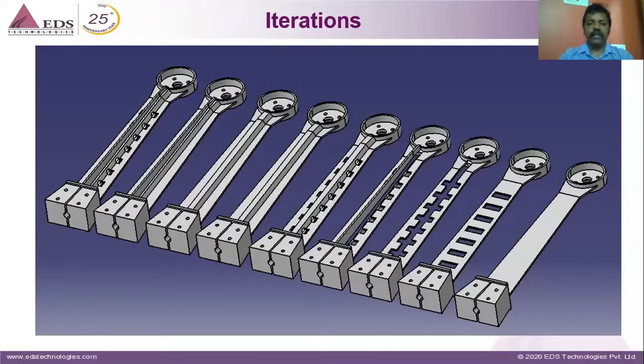So what I did is that I went and tried to add a channel kind of thing where my cable remains safe. Okay. So then later I understood, okay, having those holes was not of much use. So I removed them, because if I have this many holes, of course, I'll have to spend more time in manufacturing also. So all these kinds of things are to be considered. Okay. So then I came up with another iteration. Again, I tried with another iteration. So then finally I found that, okay, if I had some holes, of course, it is going to reduce some material. But then the kind of stiffener which I've used has, of course, increased the stiffness of the arm. So this is how we will have to do different iterations. So we end up with a final. So you just need to focus on how the first drone arm was, and then what the final drone arm is. Okay.